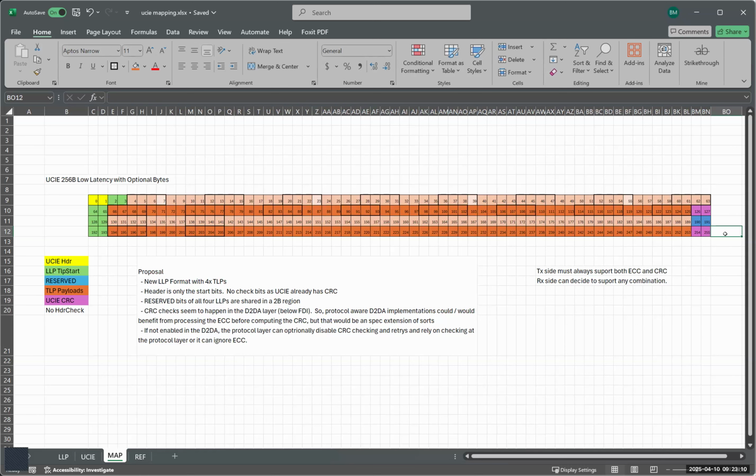I think the CRC check still happens in most controllers probably. So really what you're turning off is retry, right? And you're hoping that the errors that happen are in the bits that you have error correction for, and that you don't have too many errors. If you end up with an error that is unrecoverable in ECC, then it's a bus error, well, the bus state's bad, and you have to deal with that however you deal with that.